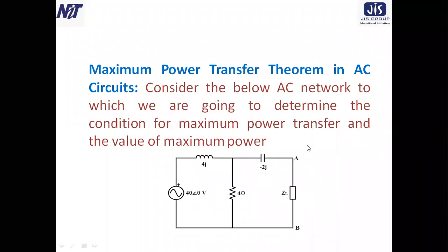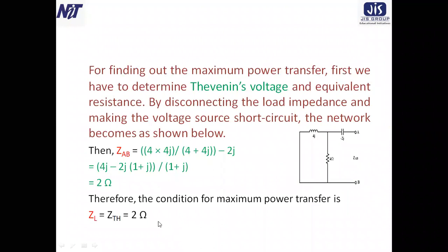How can we solve it? The first step is to remove the load resistance from the circuit, and also remove the voltage source from the circuit. That is the process to find the impedance.